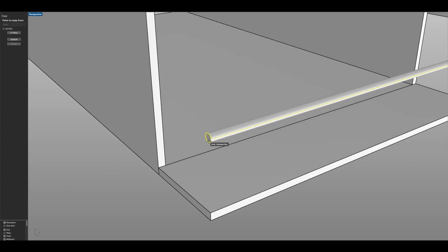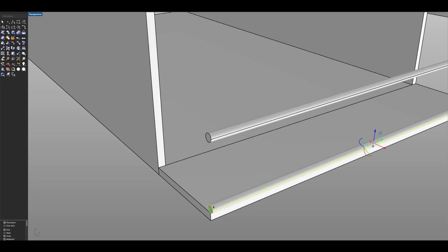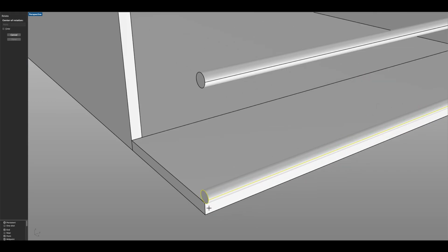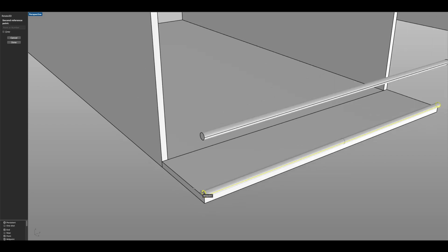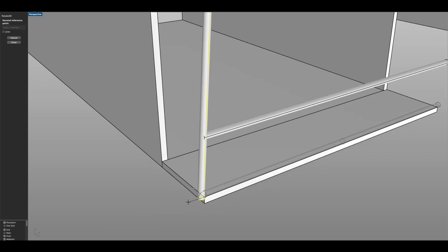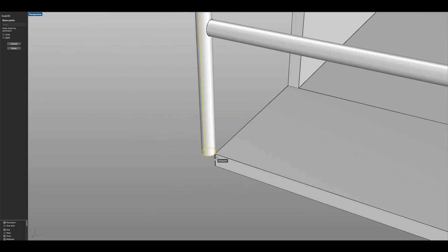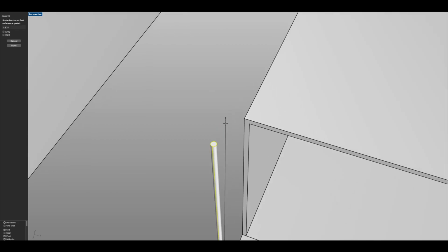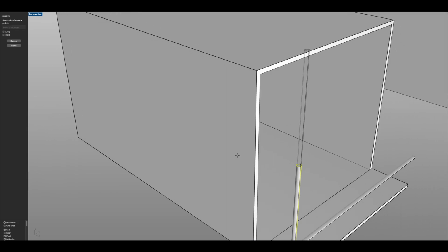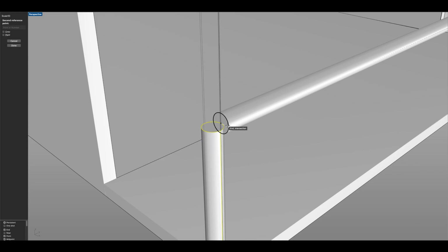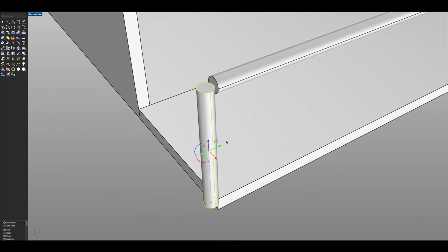Now we can make a copy of it. I'm gonna bring it down here. Actually, I want to rotate this in 3D. So rotate 3D. Let's draw our axis on this line here. Let's pick up the top of our base circle, and now with the shift key we can place this on a 90-degree angle. Let's make a scale 1D. I'm gonna pick up on this point here, bring it all the way up to the top like so, and now let's bring it all the way down at about half, as you can see here.